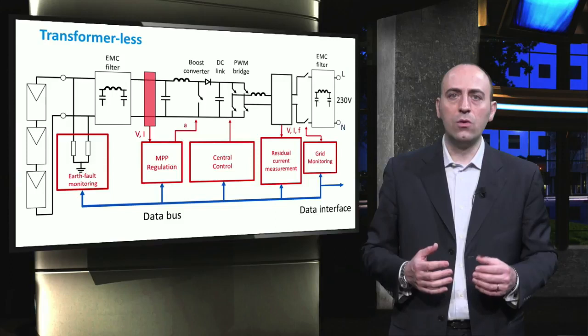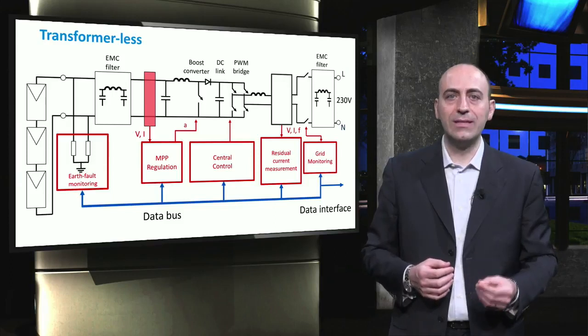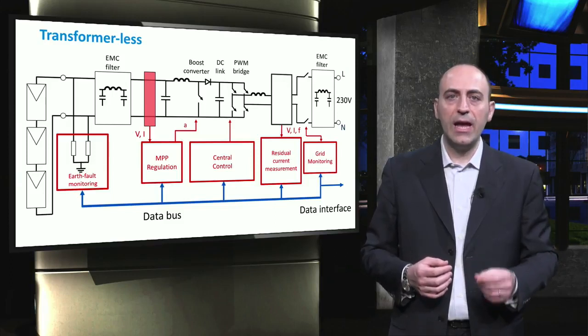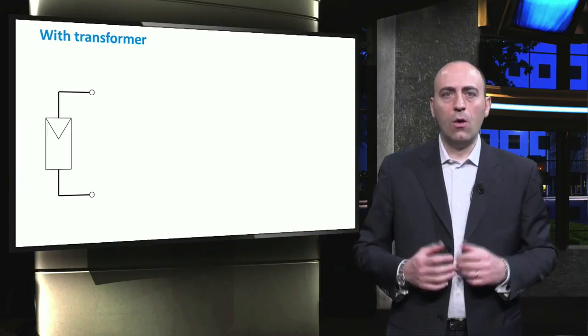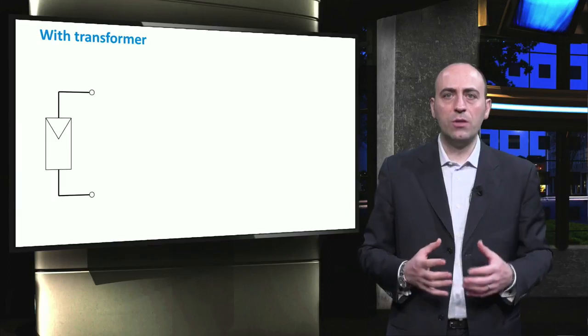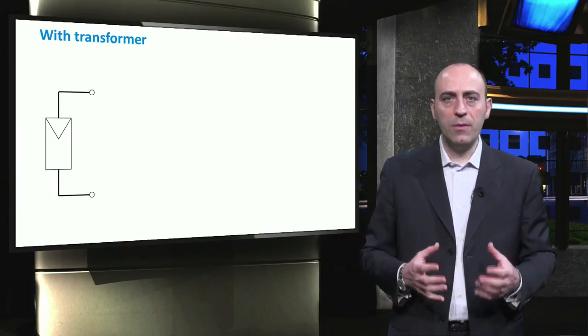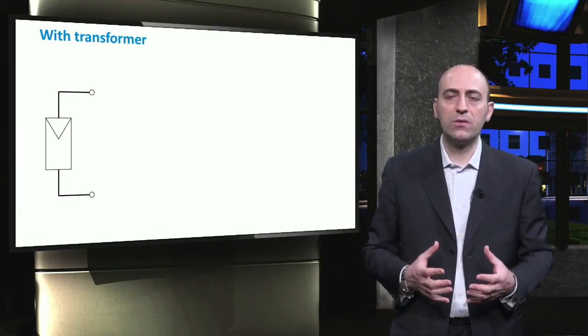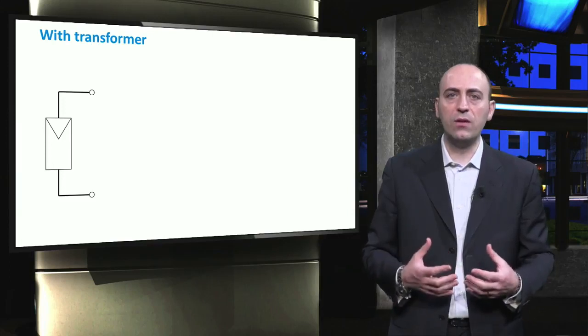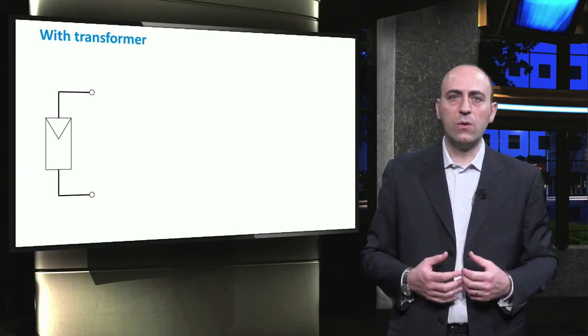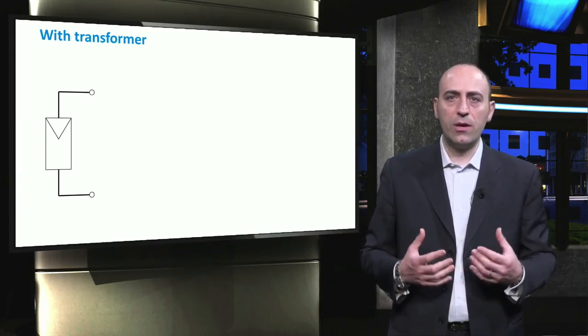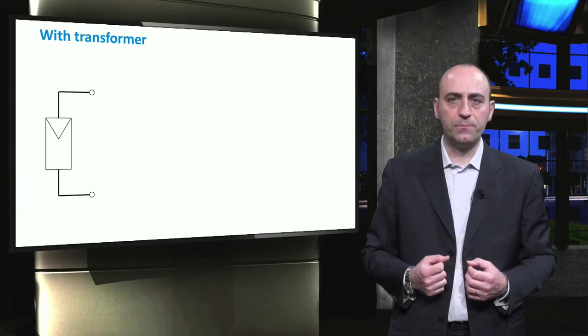Now we will look more closely at the inverters that instead feature a transformer and discuss their advantages and disadvantages. All initial string inverters were equipped with mains transformers. The main reason was that the PV generators were designed only for safety with a voltage level of maximum 120 volts. Also, galvanic isolation was a priority feature for personnel safety.